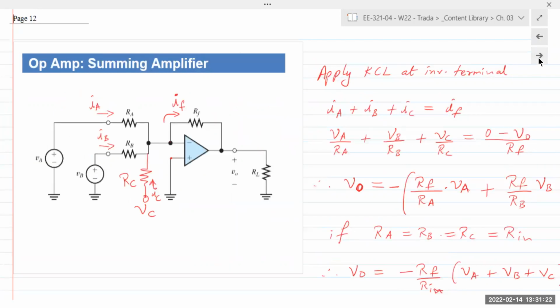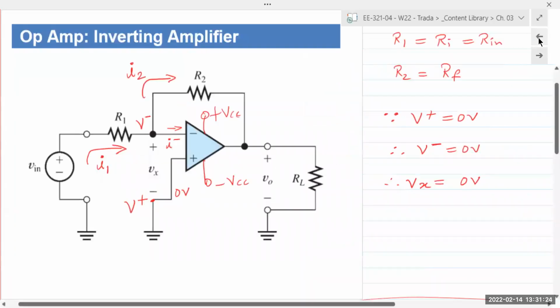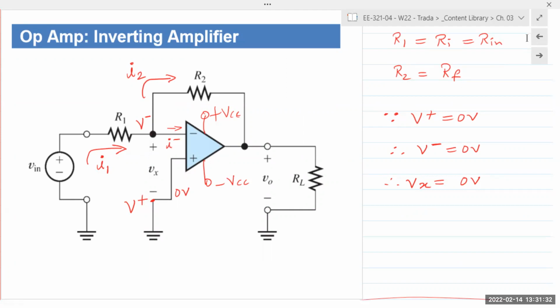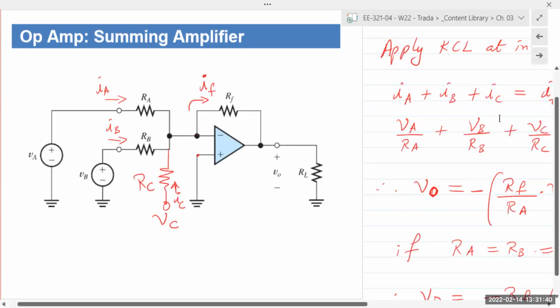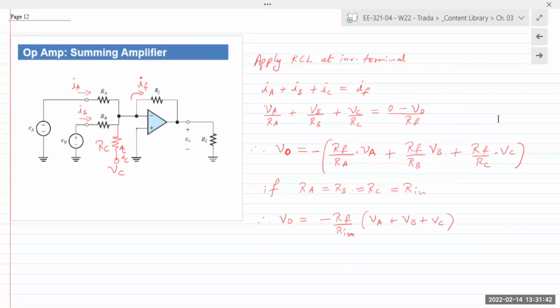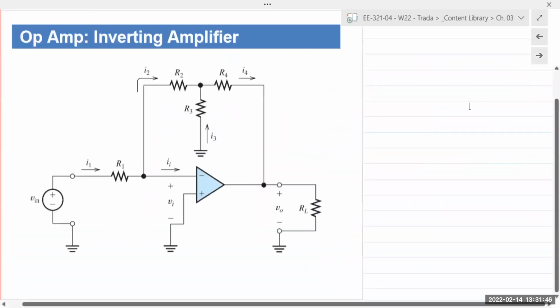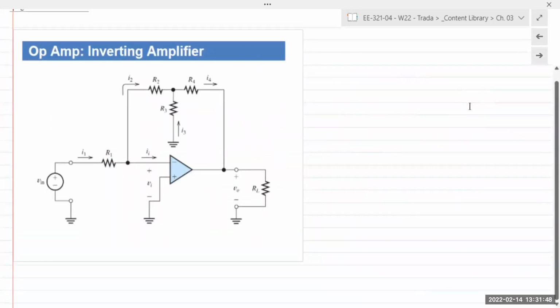Now, this inverting amplifier, what's the gain? Right? Gain is V out over V in. In terms of the derivation, we had minus RF over R1. So if we want a large gain, the ratio of the resistances has to be very large, right?